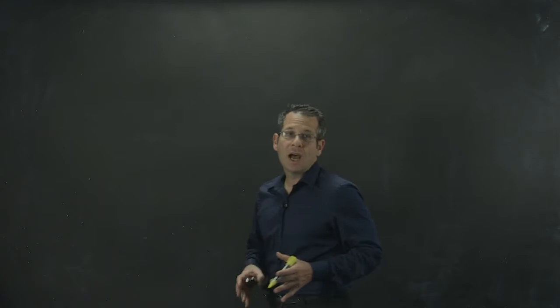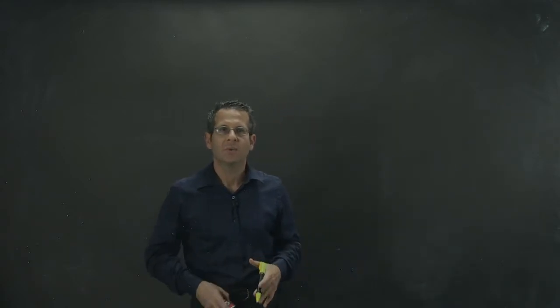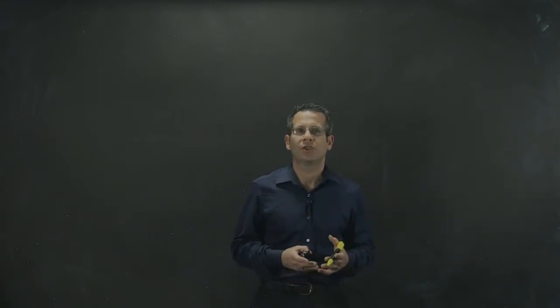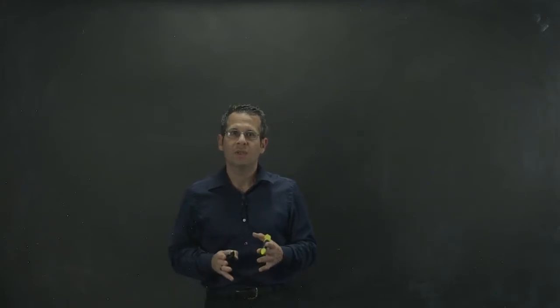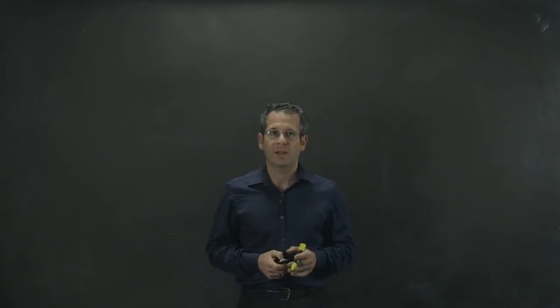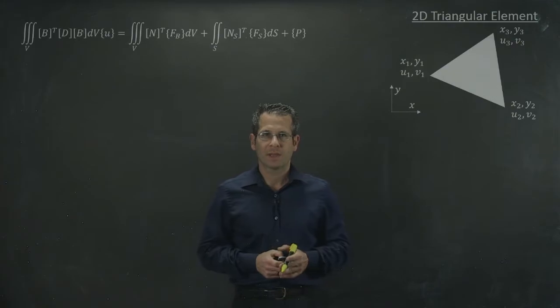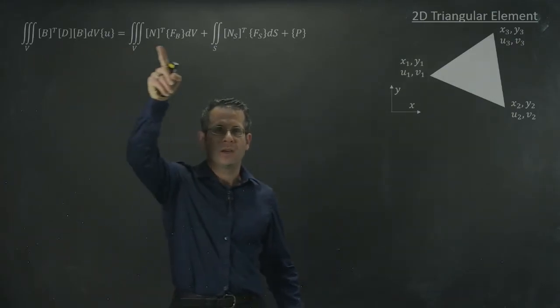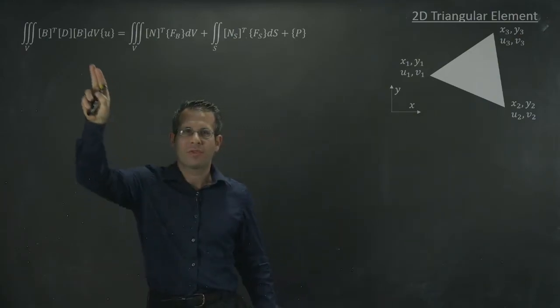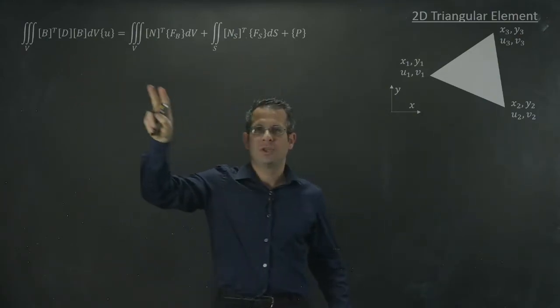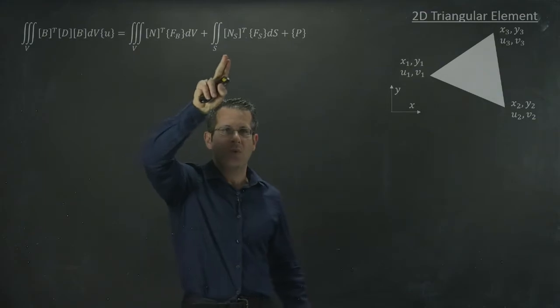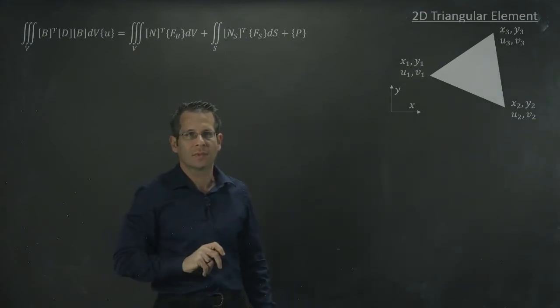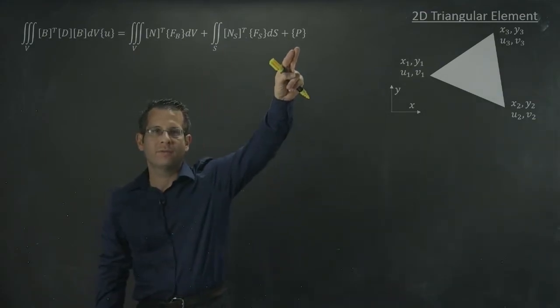In this lecture, I'd like to close some loose ends so we can start solving two-dimensional stress-strain problems using two-dimensional triangular-shaped elements. The big payoff in our last lecture was this equation, which has three integrals in it, two volume integrals and one surface integral. It also has a point force vector.